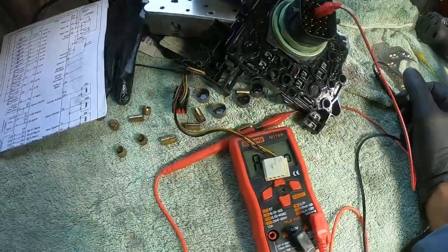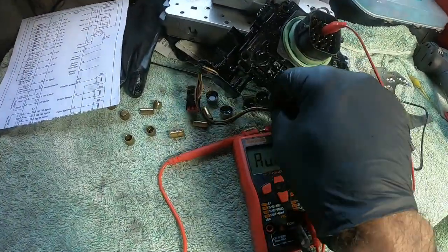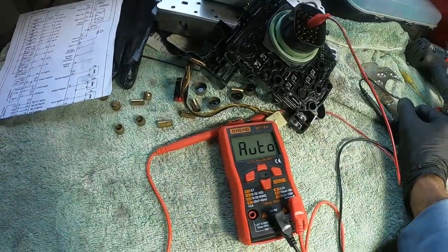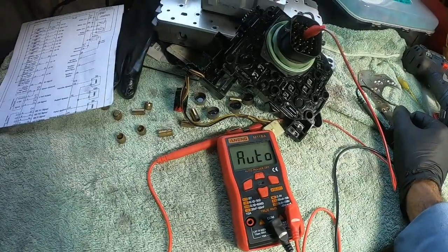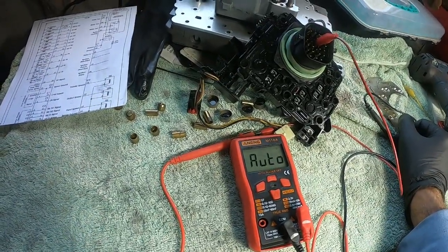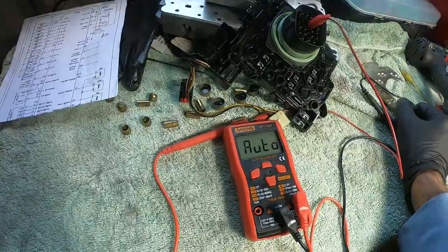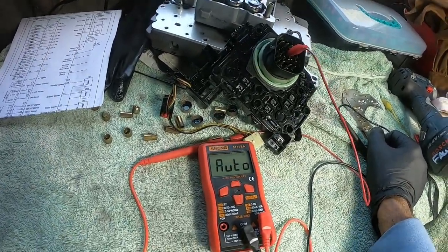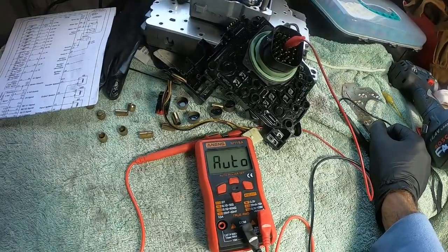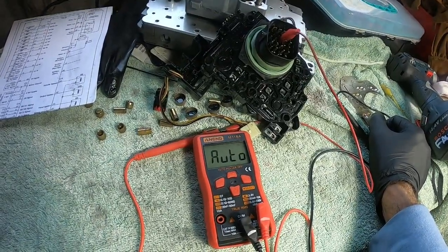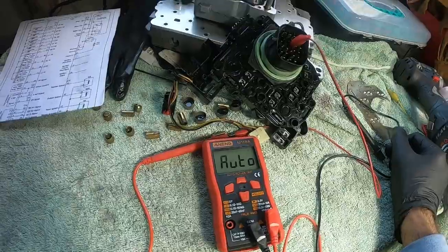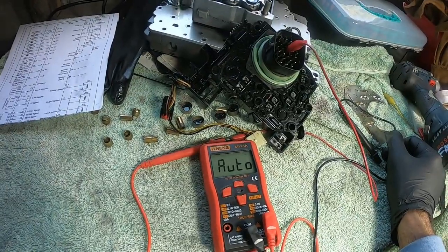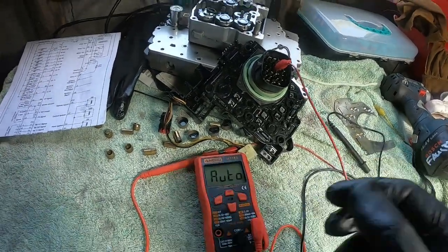This is because this is what the PCM sees when these switches are not working. So what does the PCM see when they're working? Well, the PCM sees a ground. So that's how the PCM knows that the switches are functional. So there are 2 values: either something around 11.5 because of the 300 ohm resistance, or a ground. So yeah, that's it.